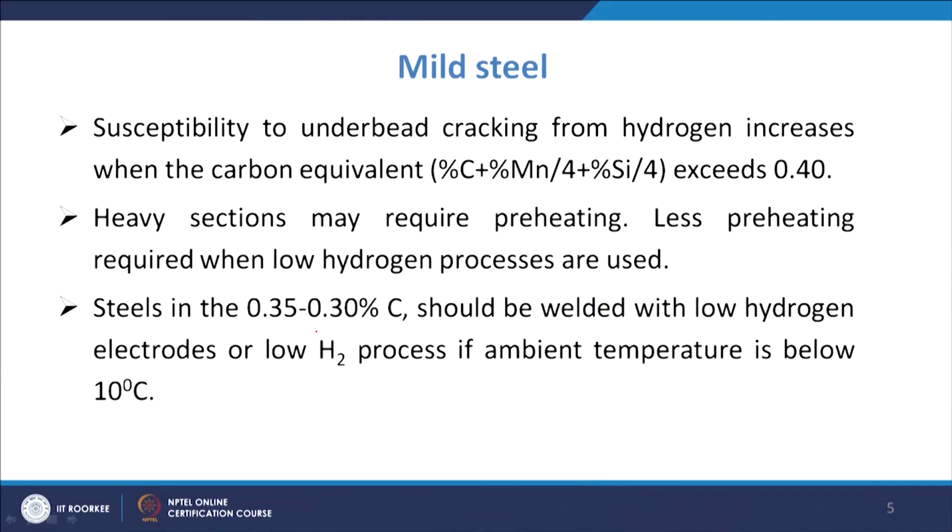Now, one more thing which is defined in this case is susceptibility to underbead cracking. That increases when the carbon equivalent exceeds 0.4. Basically, depending upon the alloying elements, whether they are going to have an effect on the carbon equivalent or not, positively or negatively.